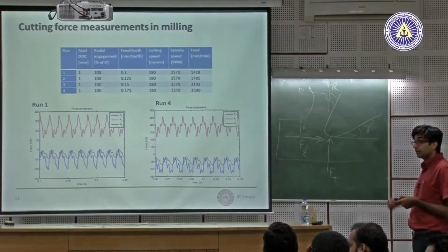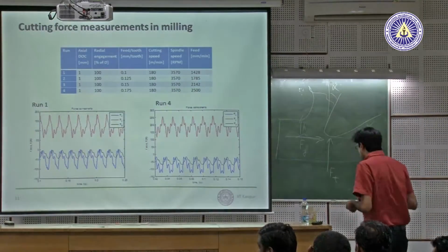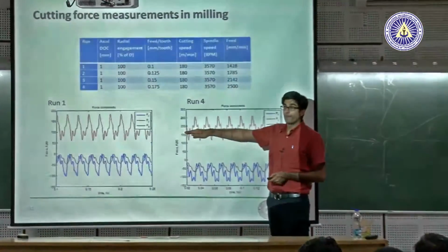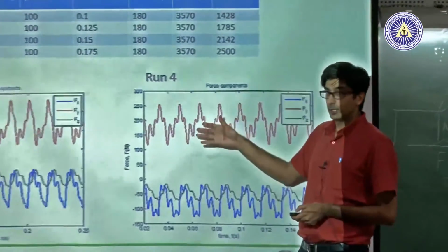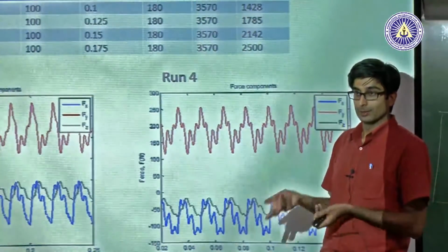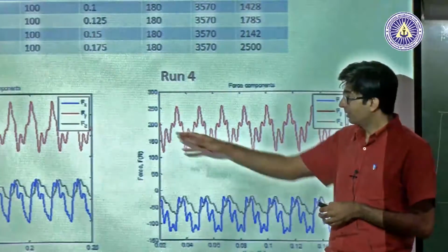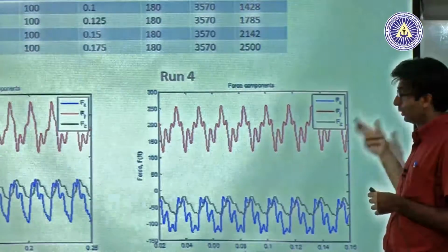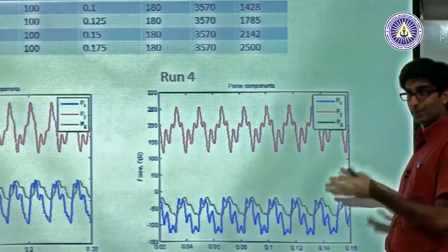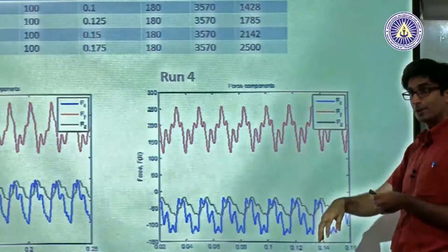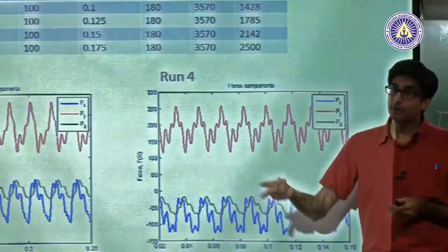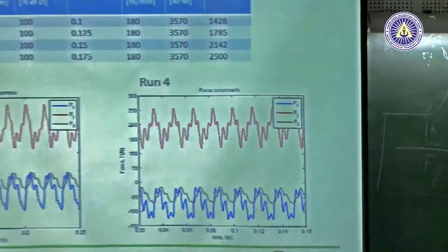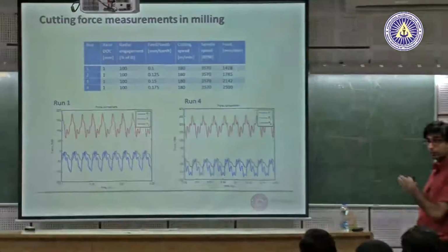So evaluation is how, from maximum to minimum? Yes, so how we can, just 250 to 150. Average, you take the area under the curve, sum it, take the mean. In this case it's 250. You can either visually eyeball it, or you can put it into a program, Excel, sum the values, or in MATLAB and say what the average is. So average in each direction, X, Y and Z. You need all 3 force components.